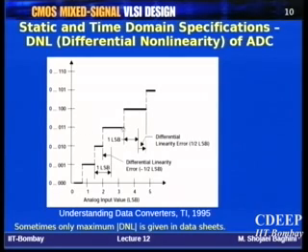The next code will be 010, and the transition point for that code has been shifted to a value 1.5 LSB above this. Therefore, you have plus 1/2 LSB DNL, differential nonlinearity.